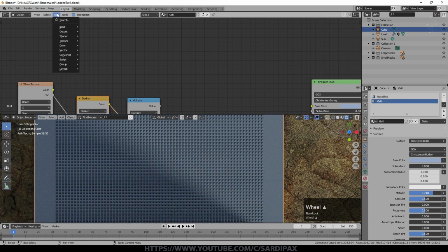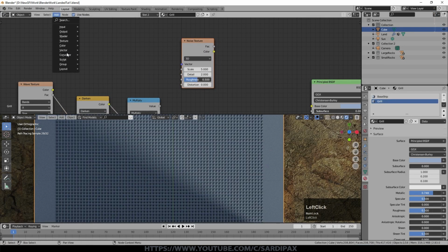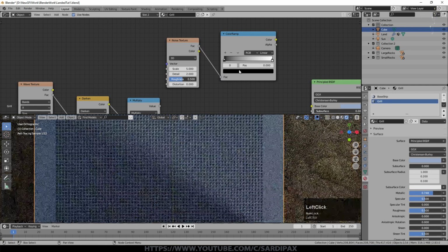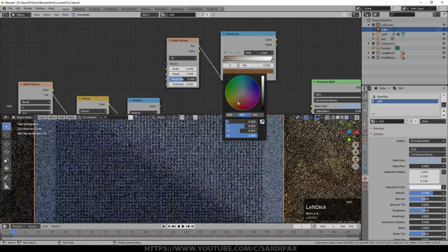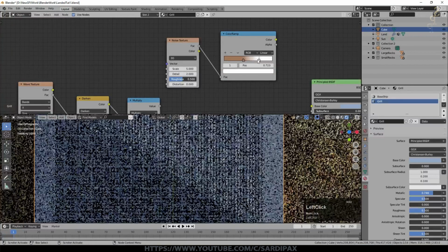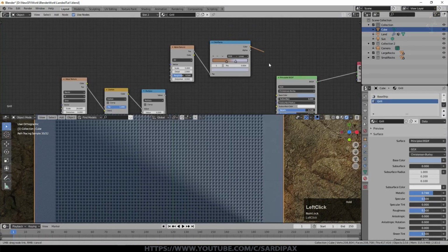So I also added another texture, which is a noise texture. I added another color ramp, noise texture, left it at 3D, and generally the defaults, took the factor out into that color ramp, but set the dark side of the color ramp to a sort of dusty, orangey, brownish color, not too far from what might have come off the landscape, and then moved the left hand pointer up and the right hand pointer down a bit, and perhaps turned the right hand pointer a slightly bluish color and off-white, and then took that into the base color.